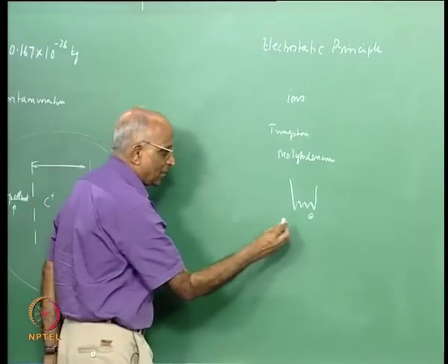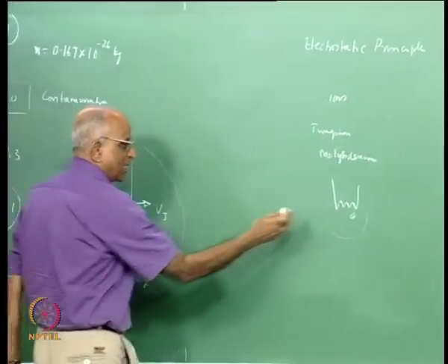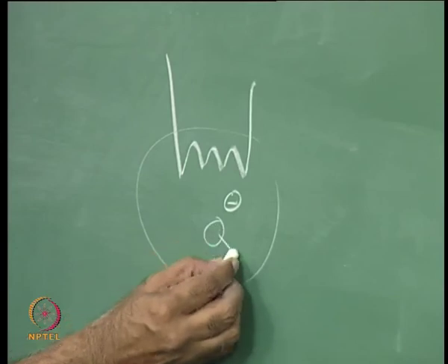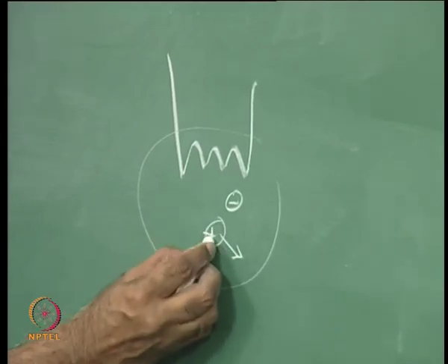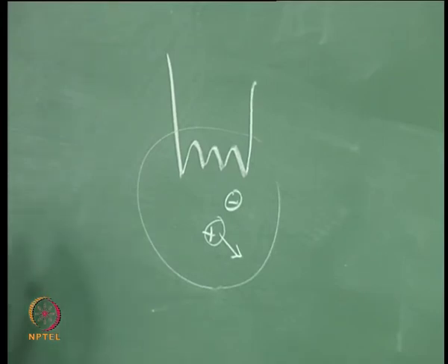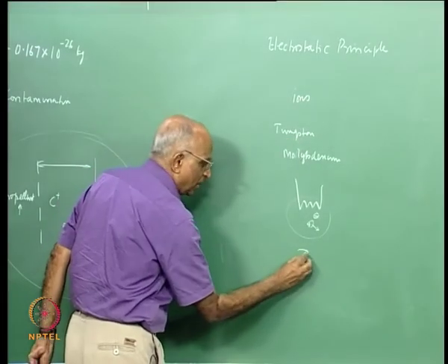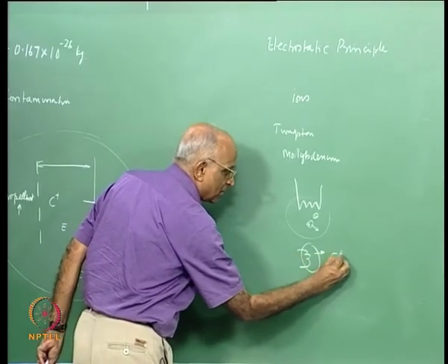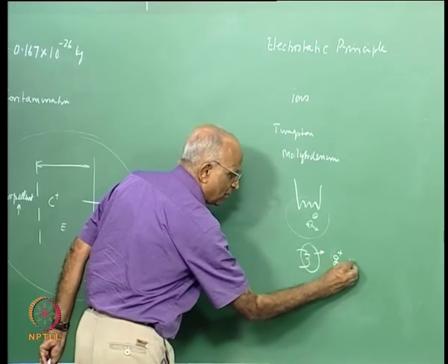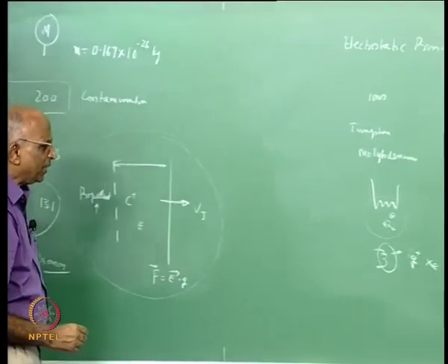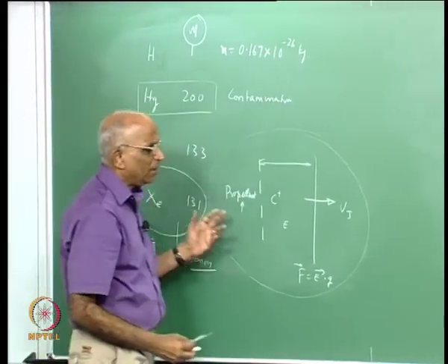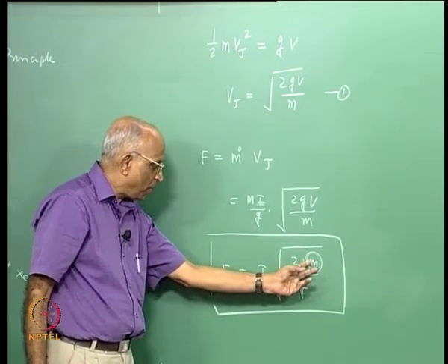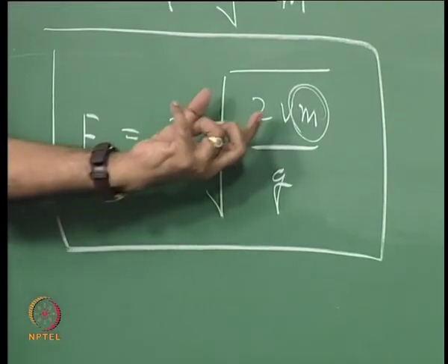When it gives out the electrons and you have a medium like xenon gas surrounding it, when an electron hits a xenon neutral atom, it dislodges one more electron from it and the atom gets positively charged. Therefore, it is easy to make use of: you heat tungsten, you put the tungsten in a medium of xenon or something, and it is possible for you to get positively charged particles of xenon coming over here. At this point in time, I must also tell you, we talked about the molecular mass of the particulates or the gas or the propellant used for electrostatic propulsion needing to be large.